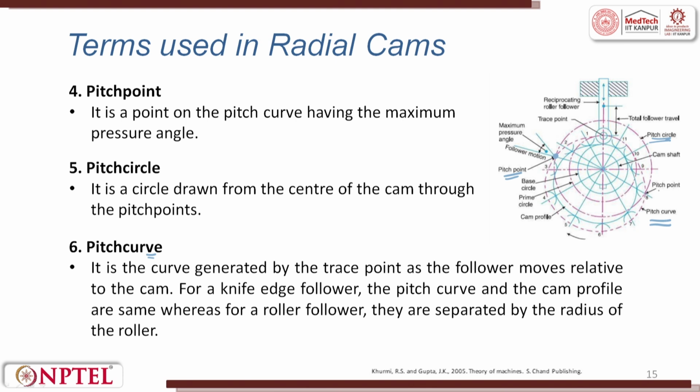See, the pitch point is here. Pitch curve is the curve generated by the trace points, the dotted lines, as the follower moves relative to the cam. For a knife edge follower, the pitch curve and the cam profile are the same, whereas in a roller, they are separated by the radius of the roller. So, you can see the cam profile, base circle, pitch curve, pitch point.